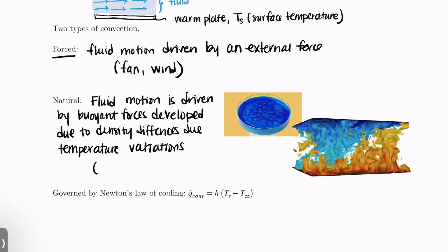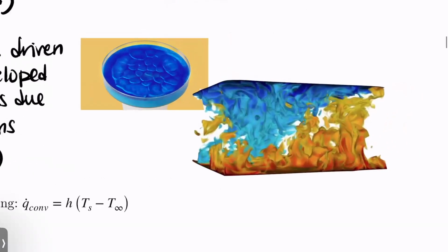All right, so the idea behind this is heat rises, right? For example, if you have a hot plate at the bottom and then a cooler plate at the top and you have a gas in between, this is the type of mixing that you observe. The gas at the bottom plate is getting heated by that bottom plate. As that happens, it becomes less dense and it starts to rise, relative to the cold air at the top that starts to sink because it becomes more dense.